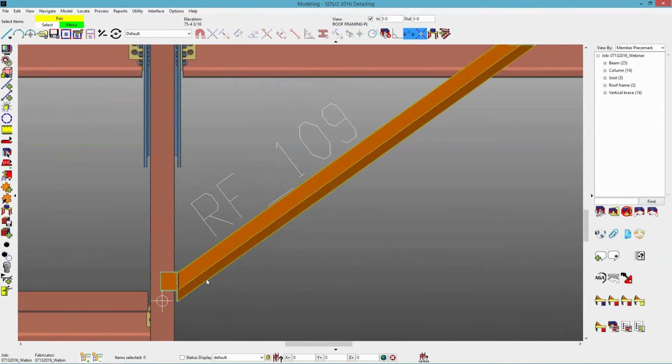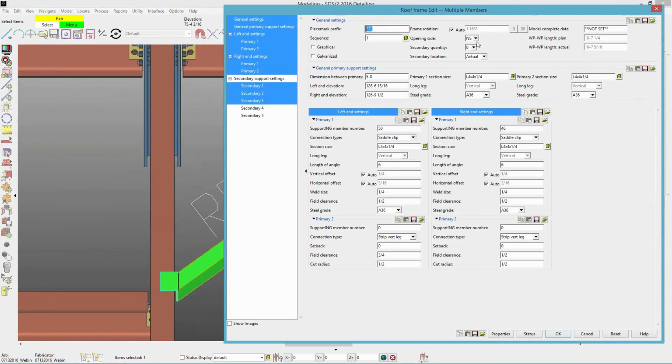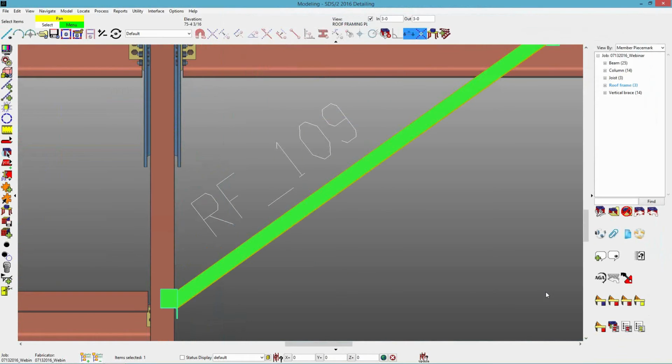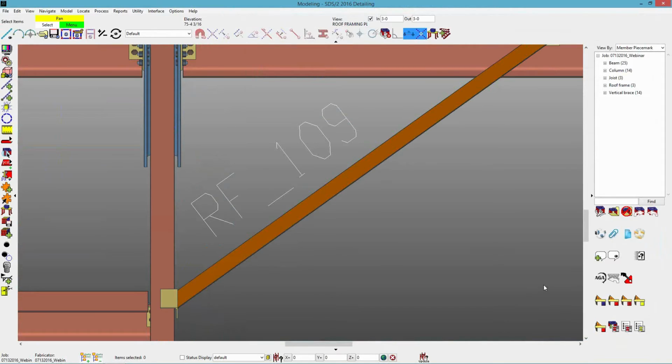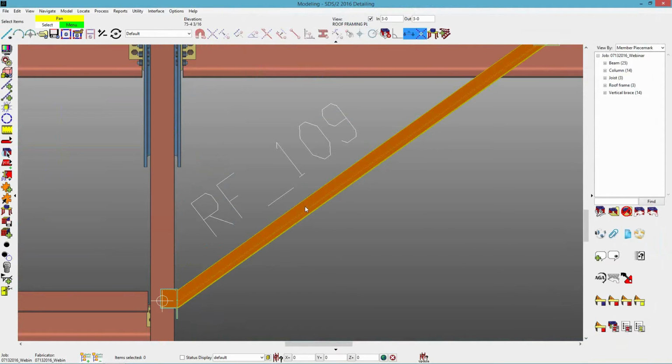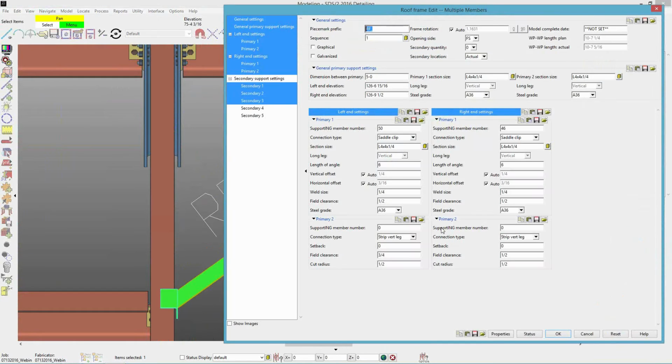So right now, in this case, my angle leg goes in maybe towards that corner opening. If I need that to go out away from the opening, I can just use my opening side and set that to far side. The way it works is that toe direction is always going to point out away from the opening side. So you can use that to change that.